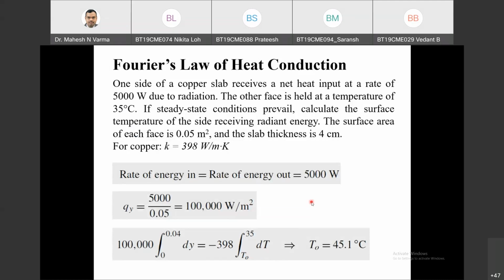What we have covered is just the definition of flux, then convective flux and molecular flux. In molecular flux, we discussed molecular flux for momentum transfer, which is dealt with by Newton's law of viscosity, and the similar law in heat transfer. Molecular flux is nothing but conduction, which can be characterized by low or no bulk motion.